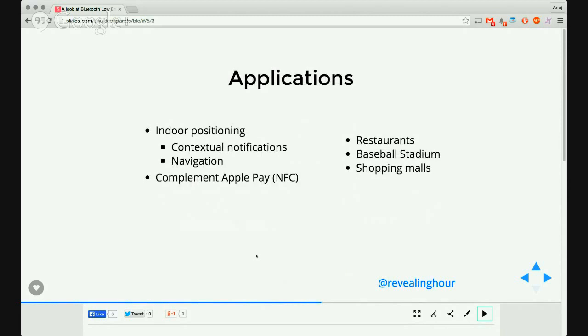So basically you are using a couple of iBeacons, or by using the major and the minor values of iBeacons, I can basically know where exactly I am inside a building. So where GPS ends, the limitations of the GPS are that it probably won't work inside a large building. So inside that, I'll use an iBeacon deployment to know exactly where I am within sub-meter. So that means I'll get centimeter level accuracy for indoor positioning. So indoor positioning is basically me knowing where exactly I'm in a building.